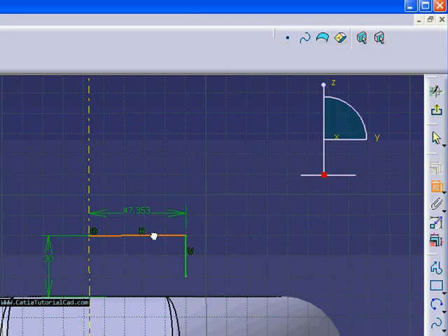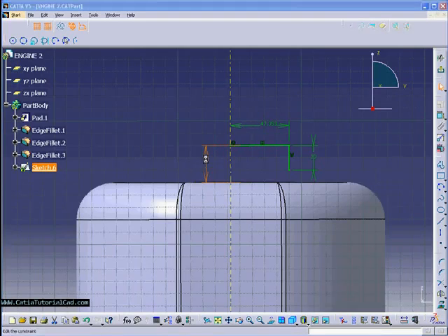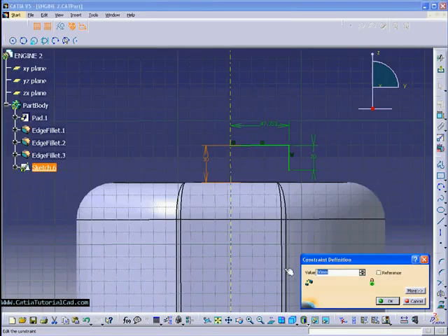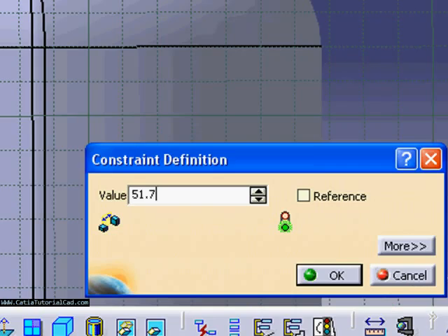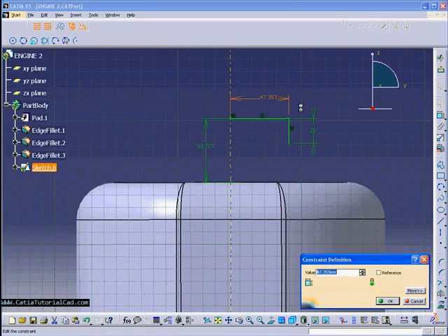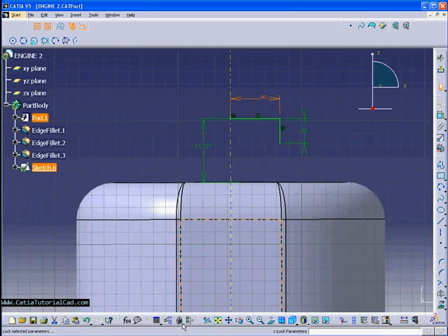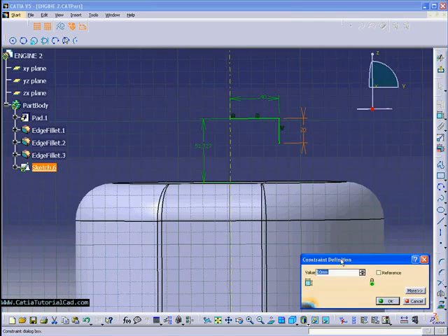Then I can just double click on those dimensions, and once I double click on it, it will give me the exact value. The first time you just put any sketch there, but don't worry about how long it is. Once you put those constraints, then you can put the values of the numbers, how big, how long, or whatever you want it.